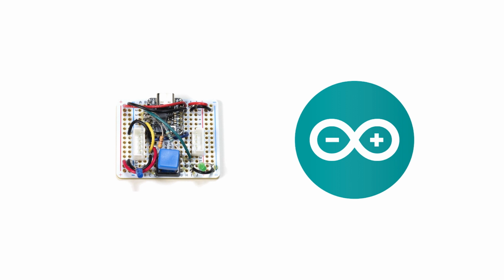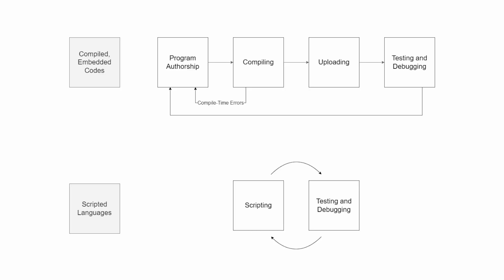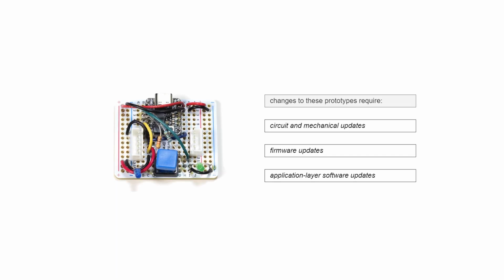Currently, the most accessible way to develop cyber-physical systems is with platforms like Arduino, which allow users to write portable embedded code. We seek to address 3 main issues with this single microcontroller compiled firmware approach. First, compiling and flashing firmware prevents interactive development. Second, single microcontrollers create monolithic systems coupled across design, mechanical, electrical, and software layers. And third, single microcontrollers run out of physical resources, such as GPIO pins are all occupied, or I2C address collisions